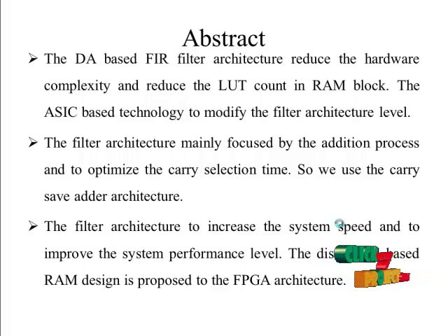is used. To reduce the partial reconfigurable time, a new architecture for the lookup table, that is LUT, in distributed arithmetic is proposed. The FIR filter is dynamically reconfigured to realize low-pass and high-pass filter characteristics by changing the filter coefficients in the partial reconfiguration module. The design is implemented using XUP Virtex. That means the design can be executed in XUP Virtex.